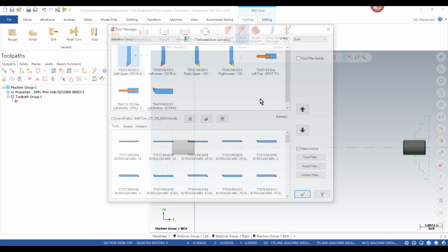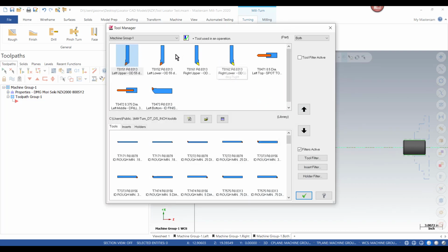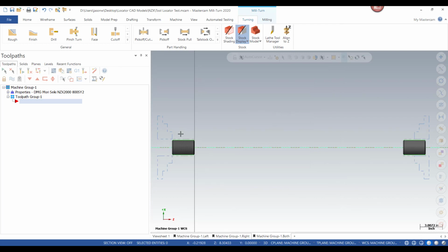In my Lathe Tool Manager, I've defined several tools to be used in the different positions. So I'm going to load all of the turning tools on position 1 with different offsets for each side and tool. And then I'm going to load 2 drills and a boring bar into position 4 of the triple boring drilling holder, each with their own offset as well. I've also gone through and just labeled them so I know exactly where they go in the tools.